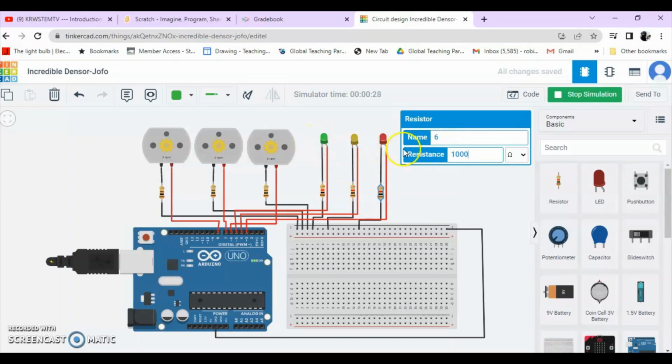When you decrease the current in the circuit, your devices will not have that amount of energy, and you will see it manifesting as a lower intensity light, as you can see here as well. Once I increase the resistance, that happens. If I increase resistance to 10,000, you can see that this resistor is even much duller now.